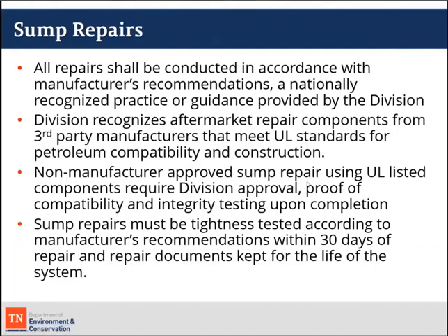And within those documents, you want to make sure, especially if you did a repair, that you document that the materials that you use to perform that repair meet the UL listed components for petroleum compatibility and construction use within a petroleum setting.